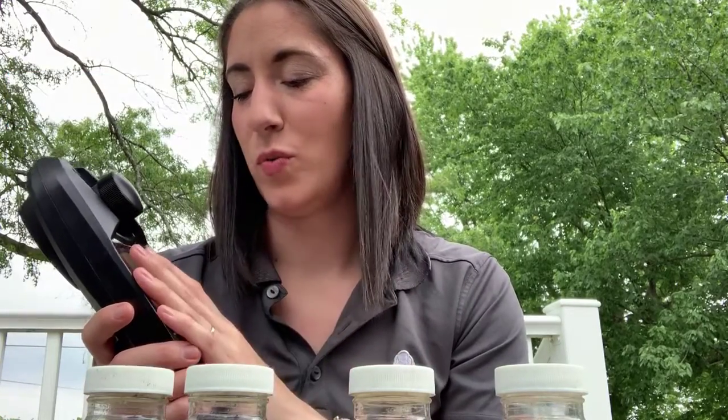So in order to test for the turbidity, what we do is we collected the 4 samples you saw on the map, and we're going to check them while we're in the field. This is called a turbidimeter. It's field size, fits right in your hand, so it doesn't require a lot of equipment. You can throw it in a truck and bring it with you. It's great for on-the-go measurements. And we're going to check the turbidity of our samples. I'm going to show you what they look like.